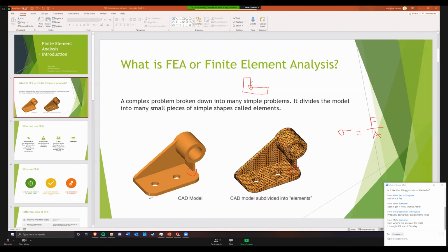As you approach that internal square edge, your cross-sectional area is approaching 0. As your cross-sectional area approaches 0, this stress value approaches infinity. So you theoretically have an infinite stress point. Now, the solver will calculate it as an infinite stress point. So you'll get a much higher stress here than you will get in reality.